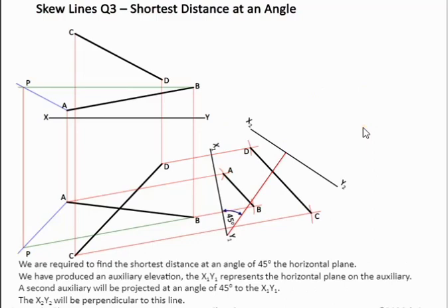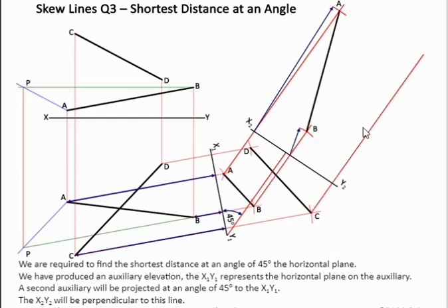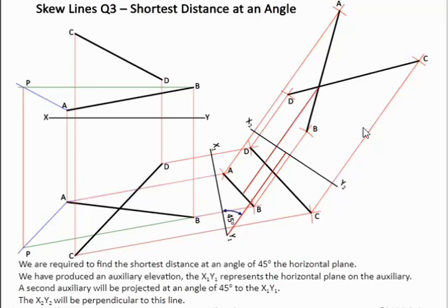So what we're doing is setting up x2, y2, and then construct our two lines, same as what we did in previous questions. So we have our two lines constructed, and then we have our point found. We bring this back, and this line now is at 45 degrees. So we bring this point back now to the two previous views, and that's our line at 45 degrees.